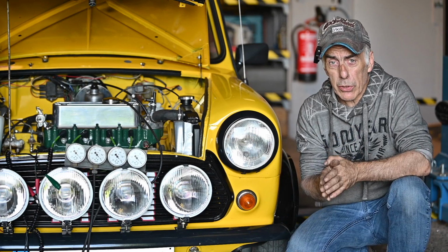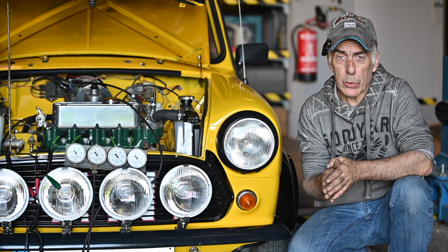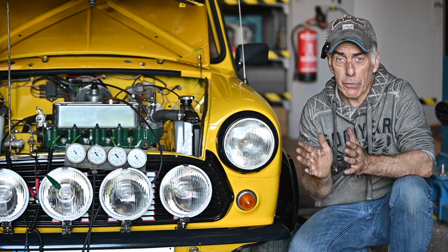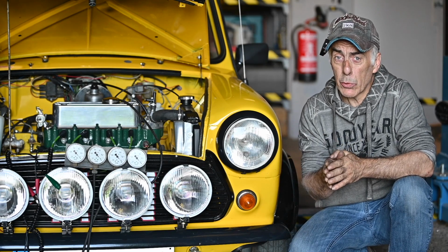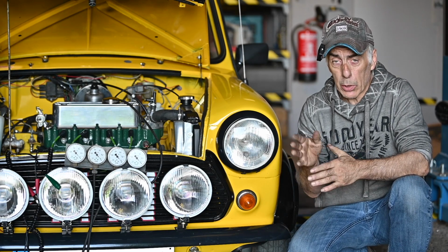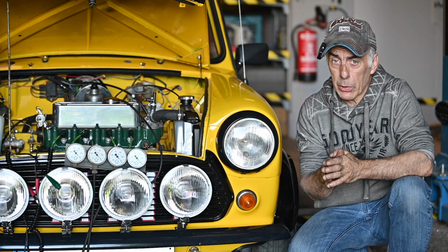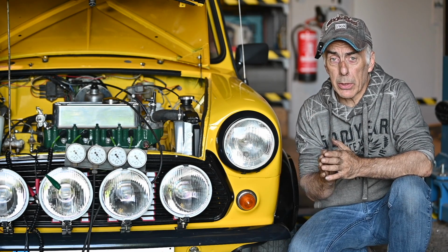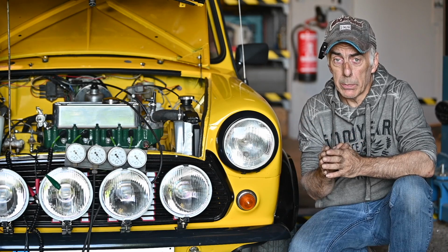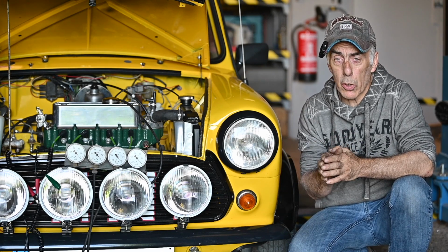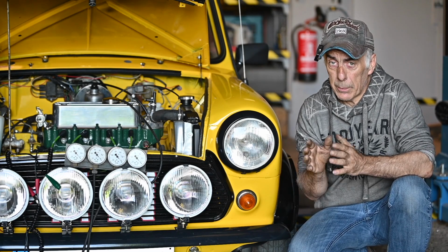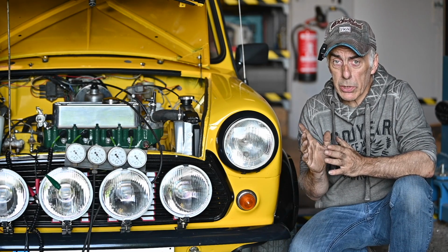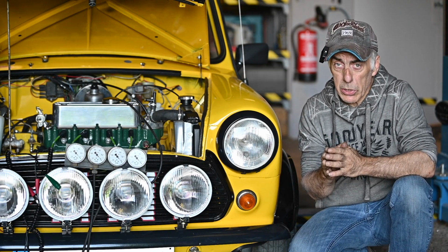So I'm going to do first the static adjustment. I'm not going to do the manual static adjustment. I'm going to use a strobe light for that. So as I said before, I do recommend that you have a strobe light. We're going to warm up the engine. We're going to run it at its idle RPMs. I'm going to loosen up the nut that holds down the distributor, and I'm going to point the strobe light to the crankshaft pulley where the mark is on, and also the pointers on the distributor cover.